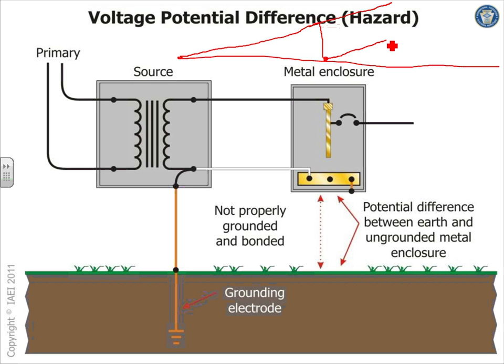And then it starts going up, up, and again, and then they bring it back, they bond it back. So long story short, on the high voltage side, say you go 2 miles, and then you find them doing, what do they do to the neutral? They tie the neutral to the ground again. Because the further away you go from bonding the neutral to the ground, the more voltage will develop between them. In the low voltage systems, you don't go miles inside a house or a building, so it's not a big deal. But that's the concept where there could be a potential difference between these 2 points, enough to knock you.